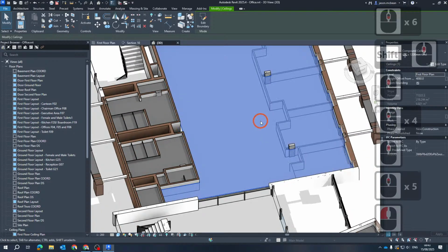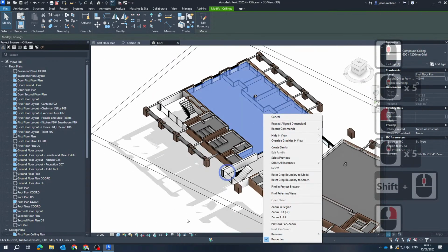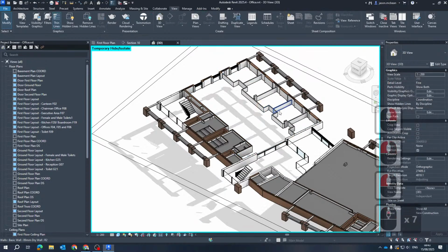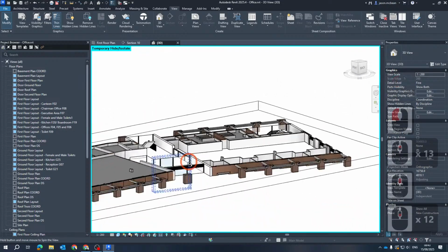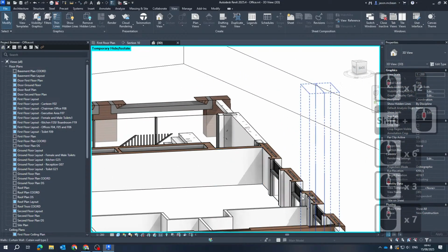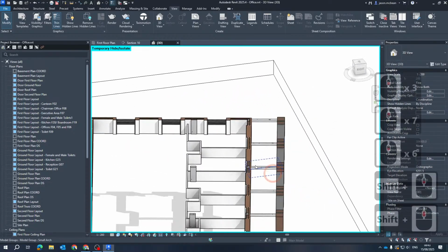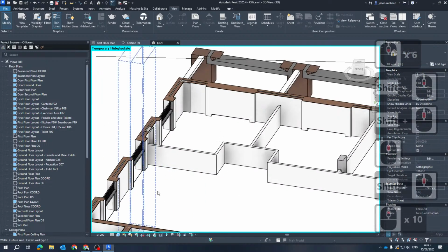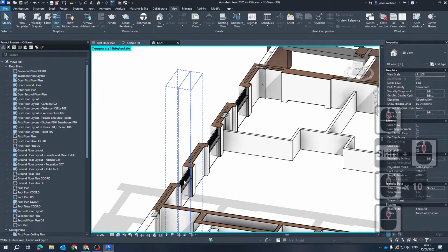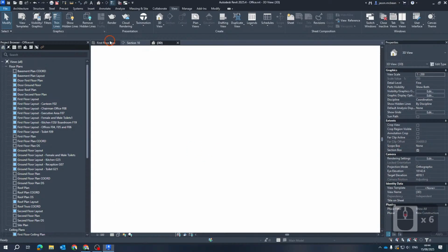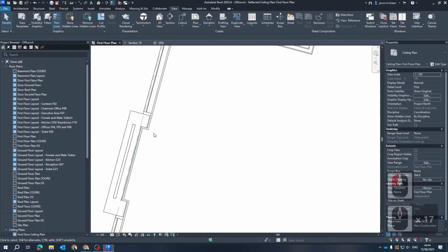Okay, so if I just select the ceiling, for example, I can hide this temporarily. So hide element. Okay, so typically some of your ceilings might vary, and sometimes when you have details like where you get a wall here, you might want a bulkhead, for example, or like a control zone, so it controls your ceiling and the boundary wall, just so that if things need to meet, sometimes it's very hard to create this pattern. So I can see one little mistake with the ceiling layout.